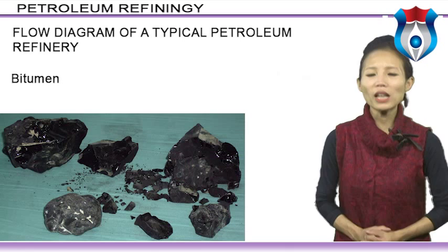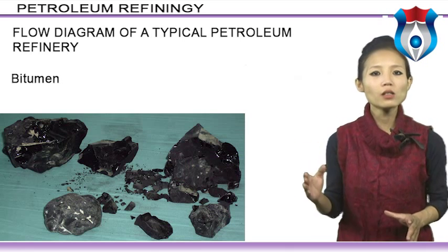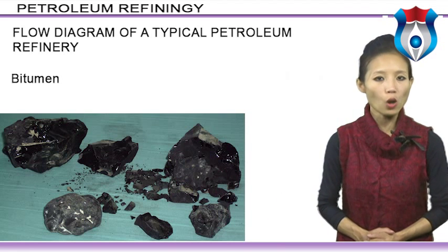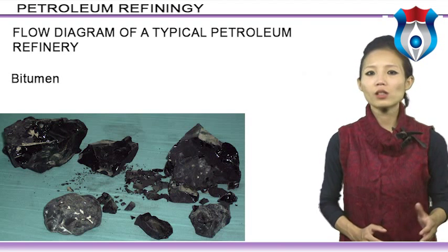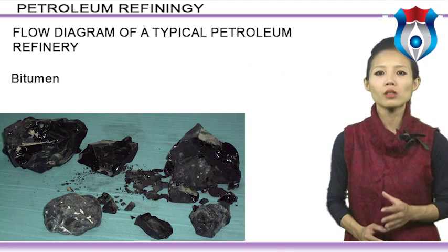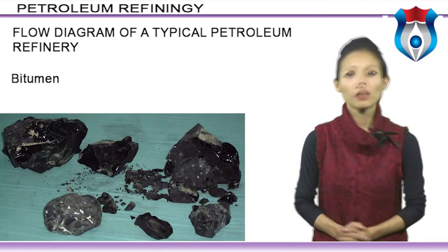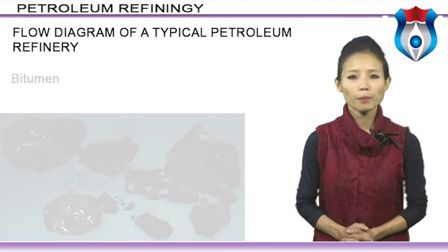Bitumen. Bitumen is a solid, semi-solid or viscous hydrocarbon with a colloidal structure which is brown to black in color. It is obtained by vacuum distillation of oil residues from atmospheric distillation of crude oil. Bitumen is often referred to as asphalt and is primarily used for surfacing of roads and for roofing material. This category includes fluidized and cut back bitumen.